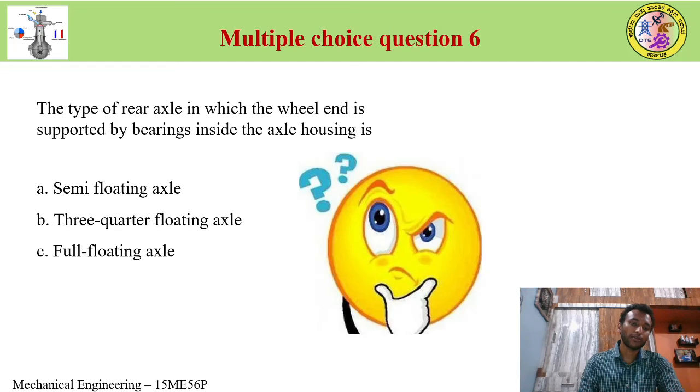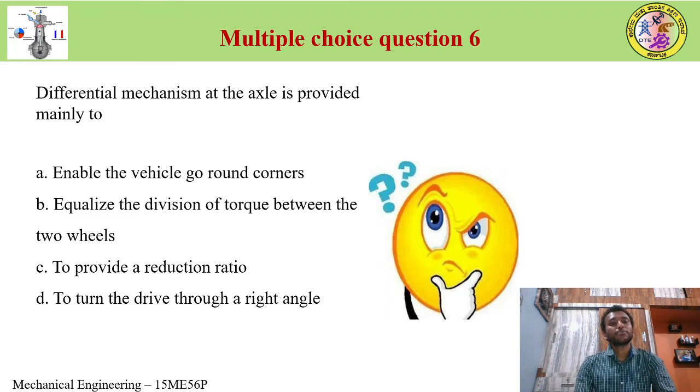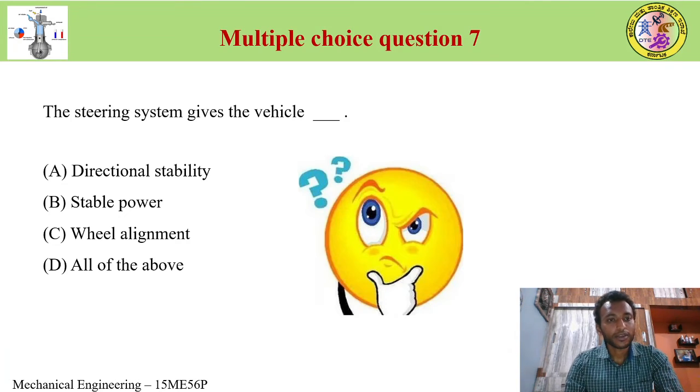Semi-floating axle, 3/4 floating axle and a full floating axle. If you look at those sketches, you can easily tell the answer as semi-floating axle. Differential mechanism at the axle is provided mainly to enable the vehicle to go round corners, equalize the division of torque between the two wheels, or to provide a reduction ratio to turn the drive through a right angle. Already we have discussed this in the previous questions: go round the corners, different speeds of the wheels. The steering system gives the vehicle...